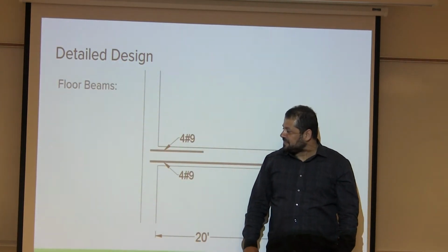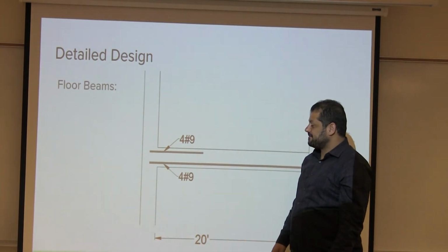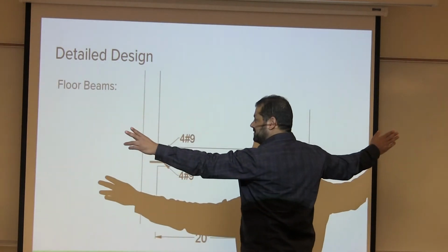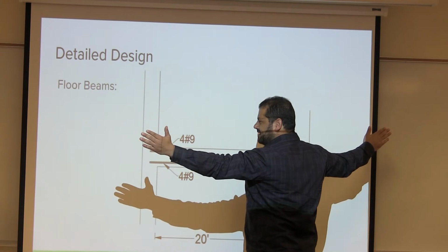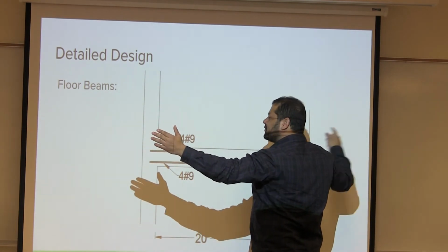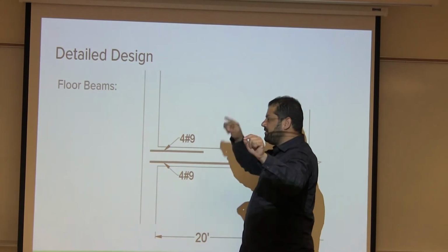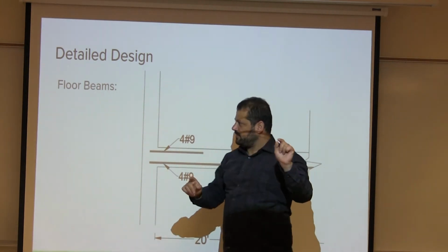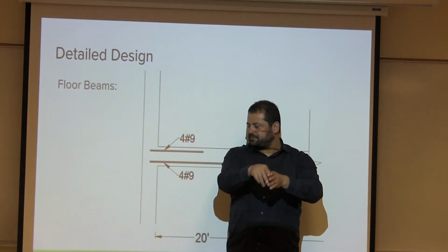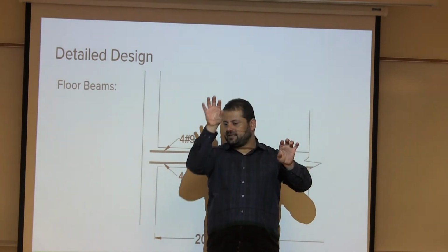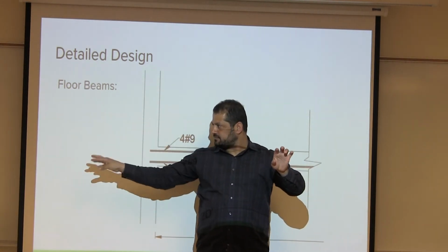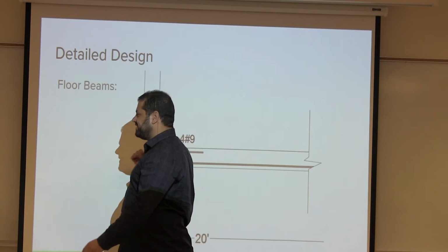So the floor beams are not both at both ends? No, just a pin sitting in there. Beam? Yeah, pin or roller sitting there, with continuation over the center one. You will have a negative moment in the middle. So zero, positive, negative. Remember, there is zero, positive, negative. But you have a moment at the beginning, right?